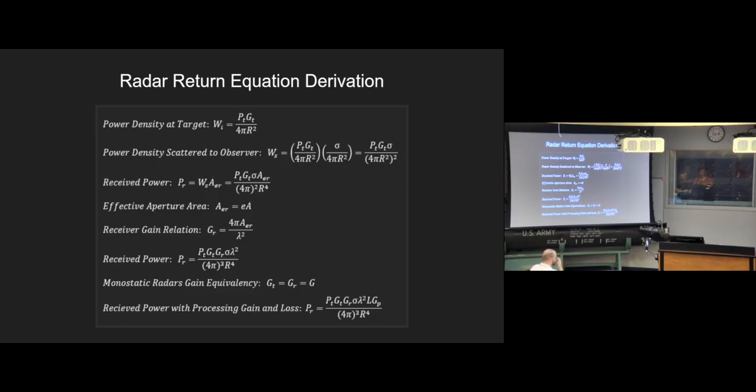All this is the effective aperture. That's because antennas have efficiency factors. If your antenna sucks, your effective aperture is going to be way lower because it's terrible. If it's perfect, this is just equal to the area of the antenna. Let's assume it was a plate, it'd be the exact area of that plate, length times width, nothing crazy.